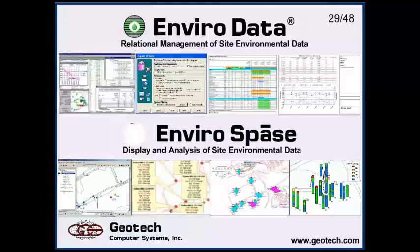I mentioned one other, a MIP probe, and that's more of an environmental tool. It stands for membrane interface probe, and you drive that down into the ground, and it basically tells you the amount of organic material you're going through. So if you do a cone penetrometer and you figure out where the porous zones are, and then you run a MIP probe down there, you can figure out whether that porosity has, for example, NAPL in it or something like that. So a combination of these tools can give you a pretty good idea of what's going on down there, which obviously you've got to know what you're doing.